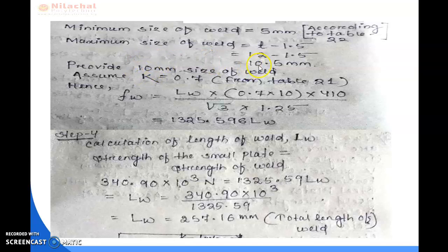From table number 21, you can get the value of K, a constant according to the fusion face angle, that is 0.7. Put all the values here: 0.7 into 10 and 410, which is the value of Fu, root 3 and gamma Mw, which we assume as 1.25. By calculating all these, you get the value of Fw as 1325.5